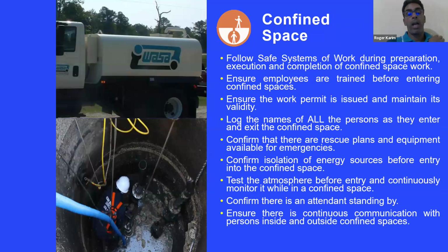Confined space: in our environment, we have to enter confined spaces, whether it's manholes, pressure filters, clarifiers, or vessels. We all are aware that confined spaces present their own risks in terms of entanglement, and persons being exposed to oxygen deficient environments or dangerous gases like hydrogen sulfide and buildup of carbon monoxide. So we always have to be careful depending on the type of space we are entering. Confined space work is done under a work permit system, there's a rescue plan in place, and there's air quality testing before you go into any confined space. The life-saving rules spell out the basic requirements of confined space work.